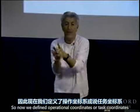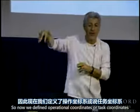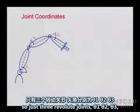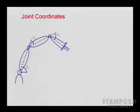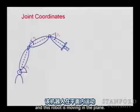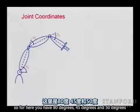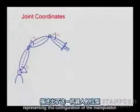So now we defined operational coordinates or task coordinates. We defined joint coordinates. And here is an example. If we take a planar robot, with just 3 revolute joints, theta 1, theta 2, theta 3, and this robot is moving in the plane, we have a sort of representation of the joints. So here you have, I don't know, 80 degrees, 45 degrees, and 50 degrees, representing this configuration of the manipulator.